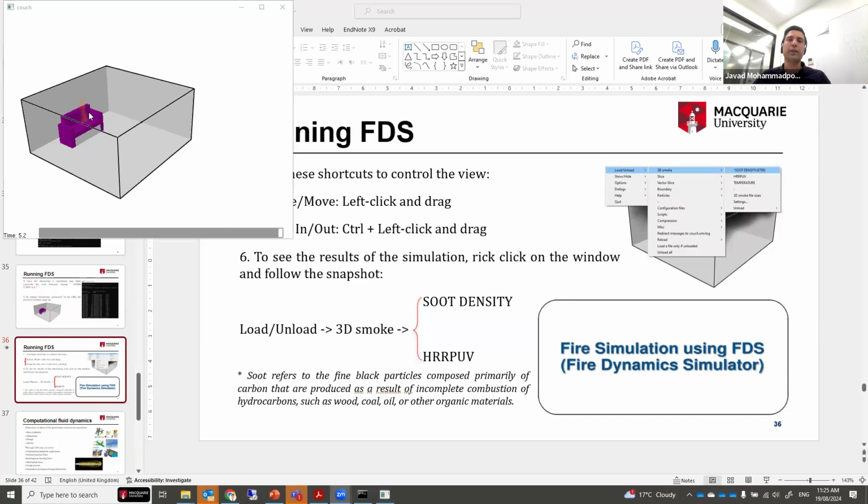Okay, so I think, Adel, you forgot to change the flow time to 5.3. In this case, you need to close the CMD file and delete all of the contents except the coach.fds in your created folder, and just open the coach.fds file, change the time to 5.3, and then run it again. Is it clear? Okay, no worries. Okay, good.